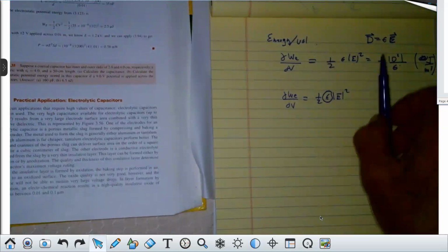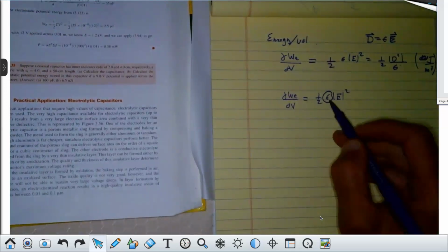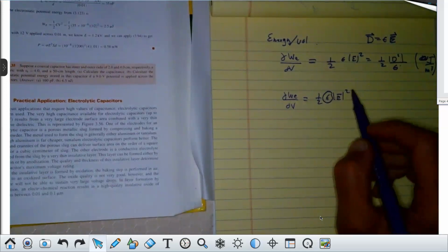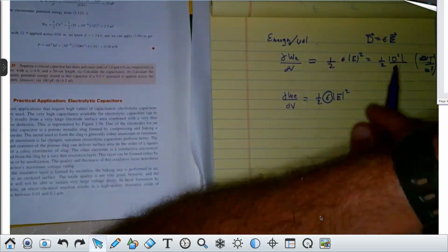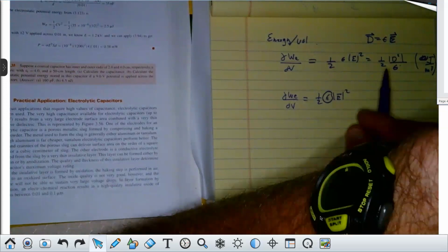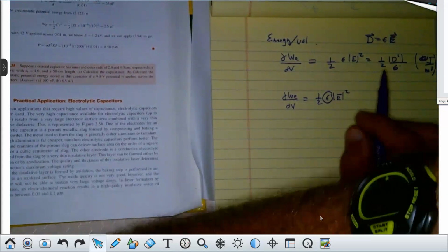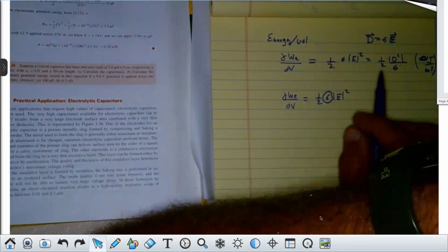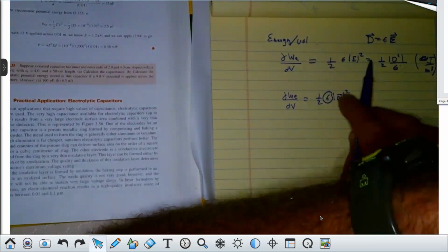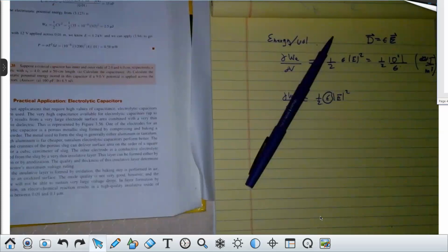And the other thing with a dielectric that I haven't mentioned, or an insulator, there's a thing called breakdown voltage. It's what voltage can it take before, or I should say, what electric field can it take before you actually get an arc? Now, you know in air that you see static electricity sparks, or you see sparks jumping whenever you touch wires together. You're familiar with that, right? Or arc welding, or lightning.